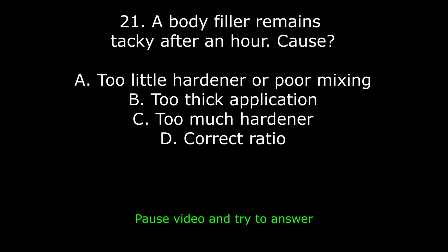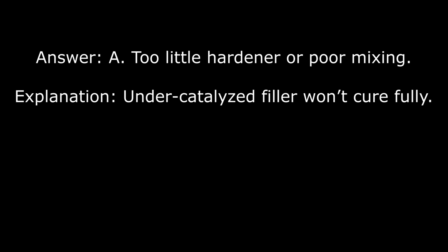21. A body filler remains tacky after an hour. Cause: A. Too little hardener or poor mixing. B. Too thick application. C. Too much hardener. D. Correct ratio. Answer: A. Too little hardener or poor mixing. Explanation: under-catalyzed filler won't cure fully.